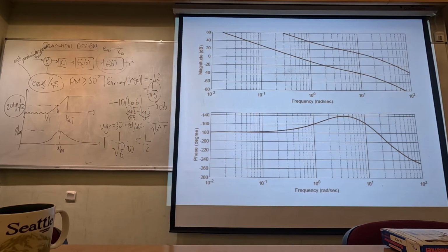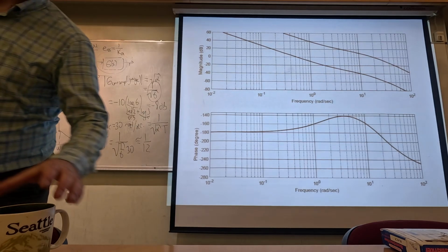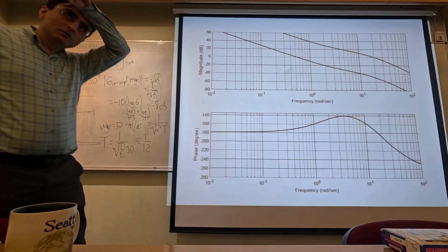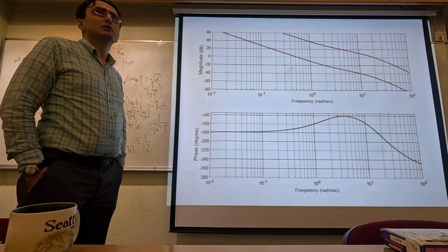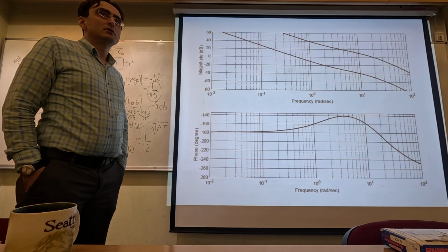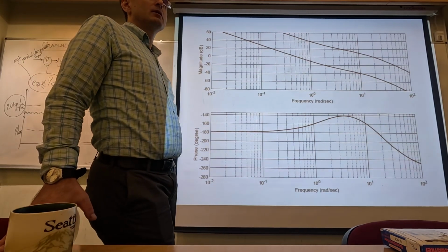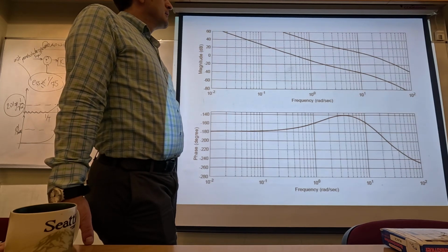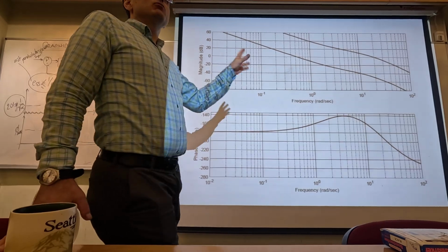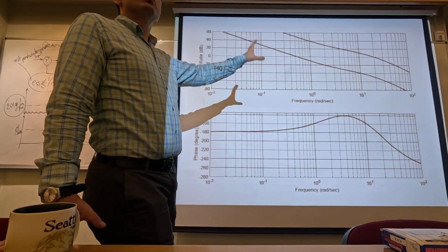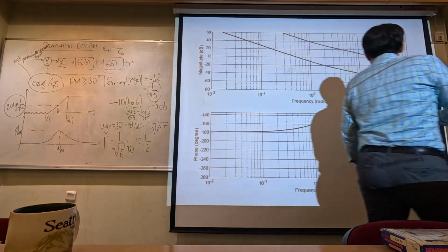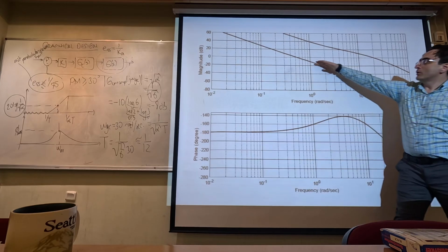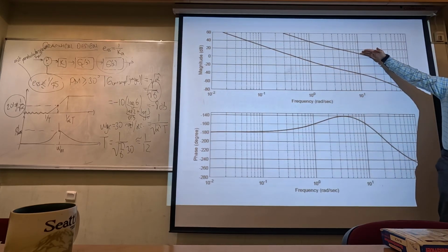Any questions? Yes. Hocam, instead of giving some error margin, can we adjust the gain within the uncompensated gain phase crossover, not gain crossover? We can adjust with K, the gain of the compensator itself, the magnitude. Yeah, by adjusting the gain, we are going to do a similar thing. For example, this system, that is the original system, and this one is with K.